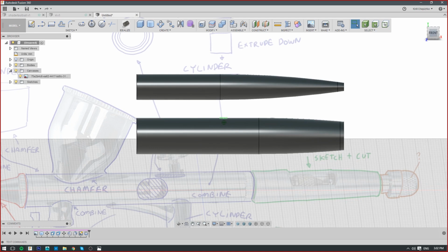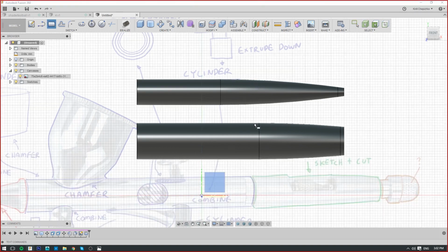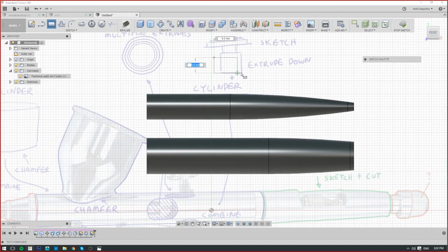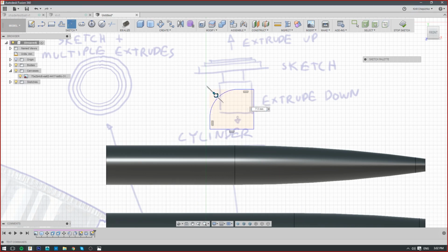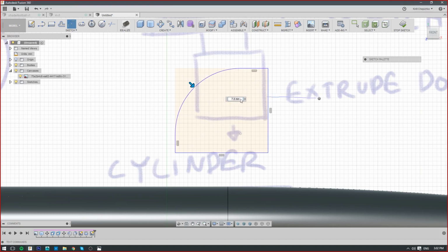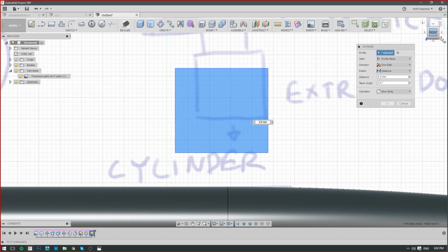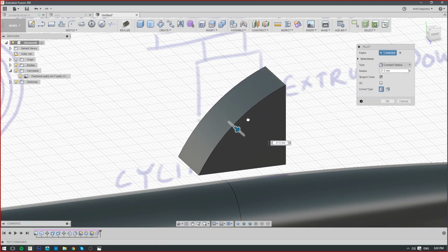So you can already do fillets in your sketch. Do you usually prefer to already do it in the sketch, or later on the model? Is it just preference? It really depends on you. Sometimes, as you already saw when I was doing it, when you start fillets in the sketch, it will mess up the sketch. But that's definitely not possible if you first turn this into a solid and then try to do that fillet. It won't let you go past that.